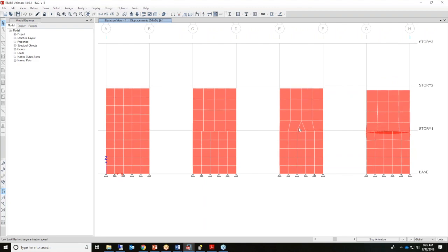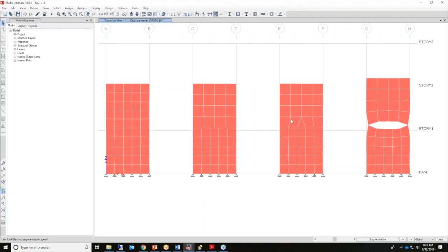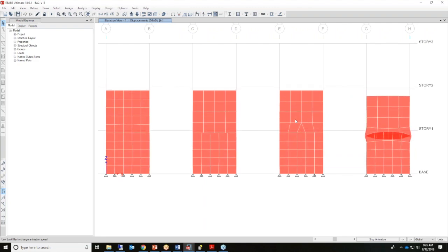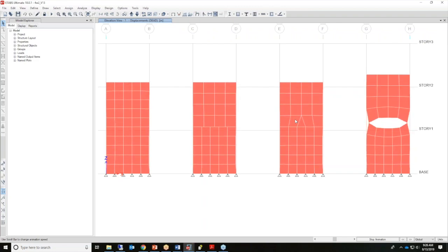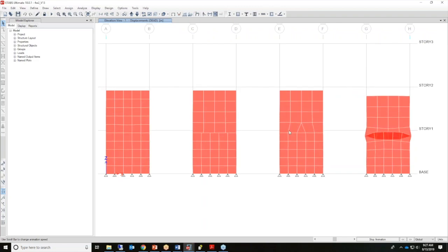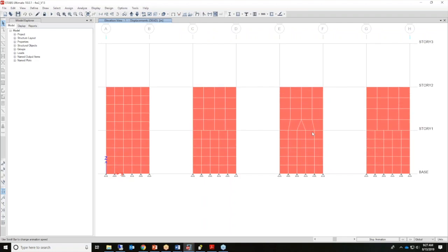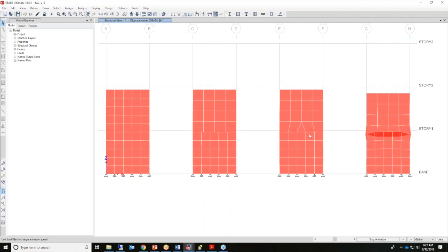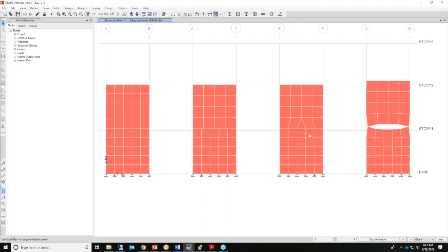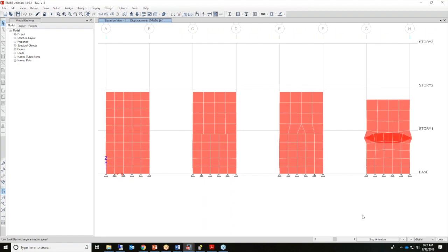This third wall is kind of a situation where I created some area objects that manually manipulated the connectivity between the nodes, which worked out fine. It takes a little bit extra time. That's why manual meshing does take a little more time than, of course, the automated internal meshing. Okay, so graphically we can see how the auto edge constraint works. What about load distribution? How's the load getting from the top of the wall to the bottom?